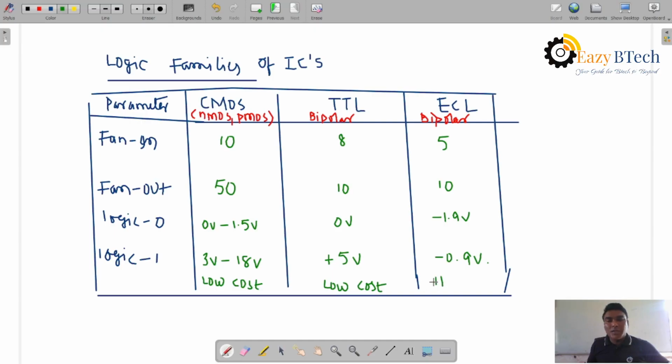And this is high cost, the designing of this bipolar transistor in emitter coupled logic ICs, right? It is a high cost based circuit, though conventionally it is high speed. The other parameters are cost and speed. Speed is also high, low power, low cost in CMOS technology, right? TTL and high speed we won't use. Nowadays we are not using this emitter coupled logic.